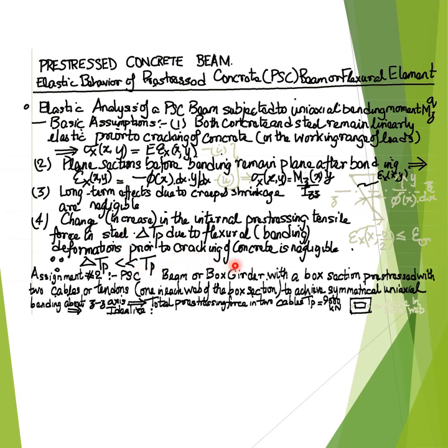That is, prior to cracking of concrete only. Therefore, assumption number 4 is valid only for pre-stressed concrete beams and not reinforced concrete beams, and valid only prior to the cracking of concrete.